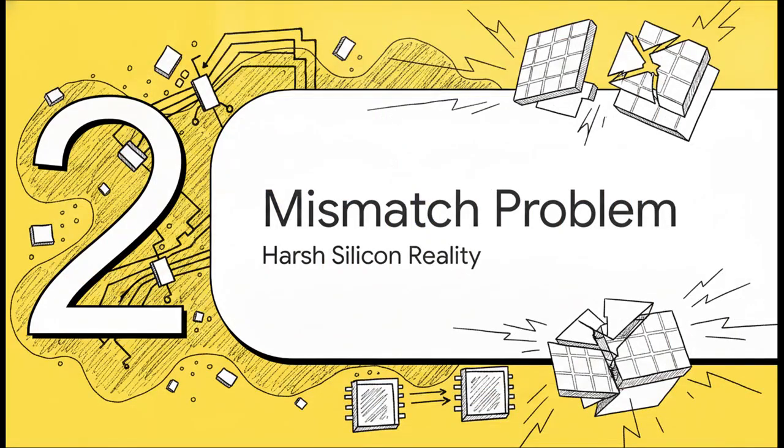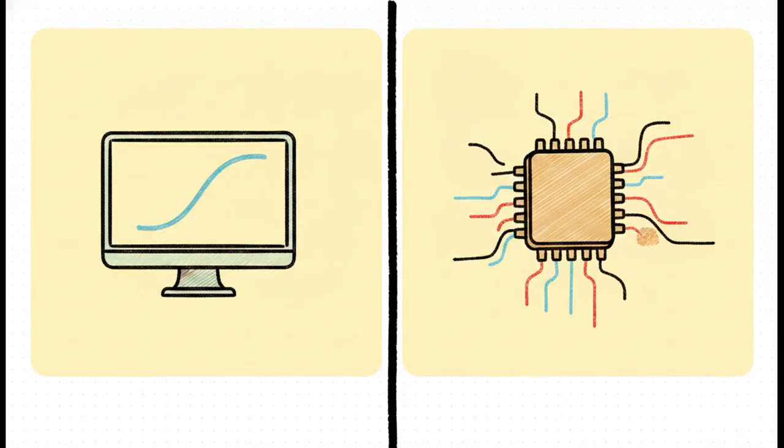Moving on to Section 2, the layout mismatch problem, the harsh silicon reality. So, what happens when that perfect theoretical recipe meets the chaotic physical reality of chip fabrication? Well, the crucial point here is that a beautiful 10 microamp simulation on your computer screen can easily turn into a broken 11.2 microamp or even a severely deficient 9.4 microamp reality on fabricated silicon. Why does this happen? I mean, the schematic is flawless, right? The issue is layout mismatch.